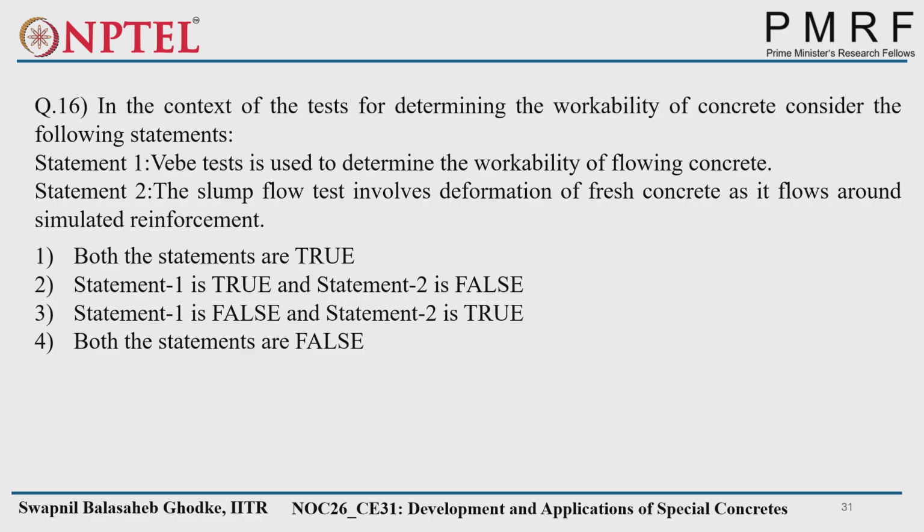Any other? Statement 1 is obviously false because, as we previously said, the VB test is only used for stiff concrete. We saw that image also. That's why we need to give vibration to get the flowability of that particular concrete. So the VB test is not at all useful for the workability of flowing concrete.